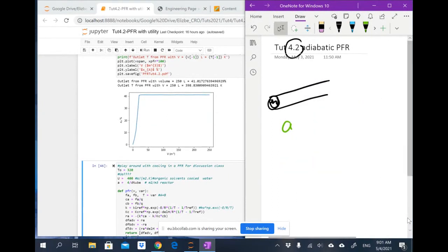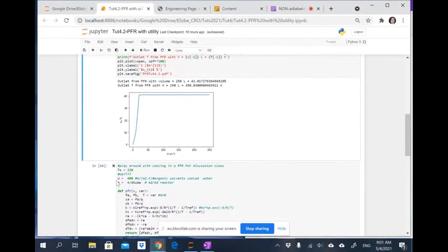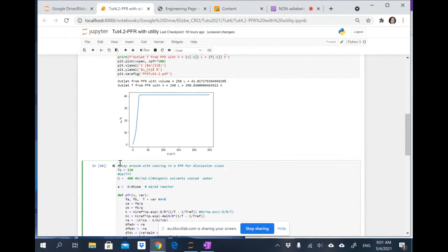This is fantastic. Okay. So let's now just go back to our code to implement this. Now, of course, it's going to give me an error because I, the design engineer, must choose the tube diameter. It's one of the design decisions I must make. And of course, this is going to impact lots of variables in your reactor. It's going to impact your pressure drop, your heat transfer area, and later on after the recess, you will see it can also impact the degree of mass transfer limitations that we have. So I'm just going to choose a 25 millimeter tube. This is about an inch.